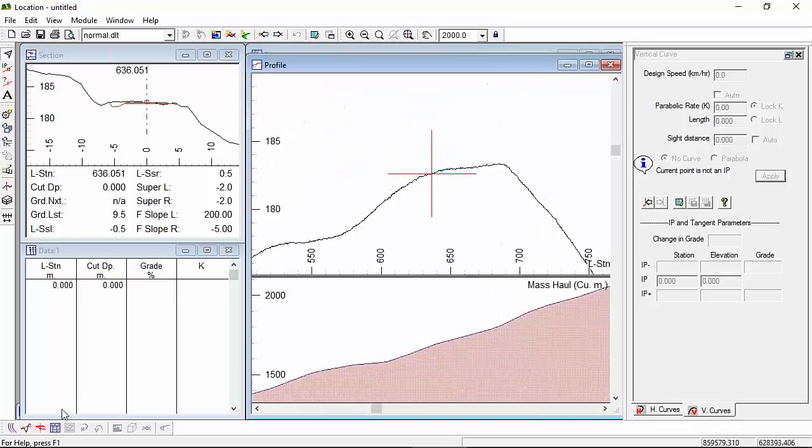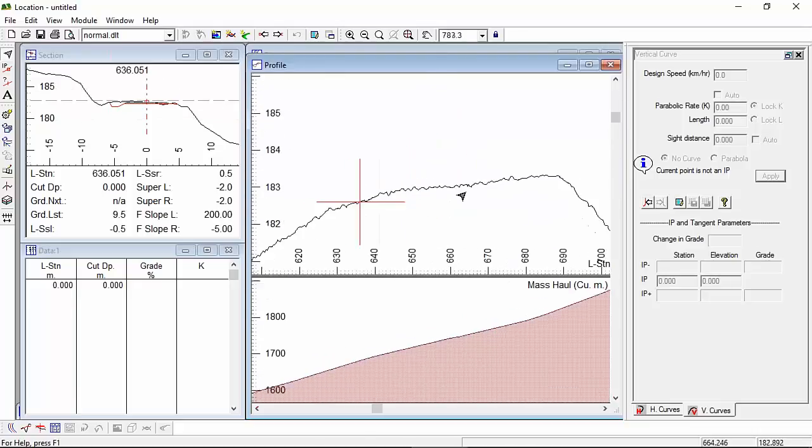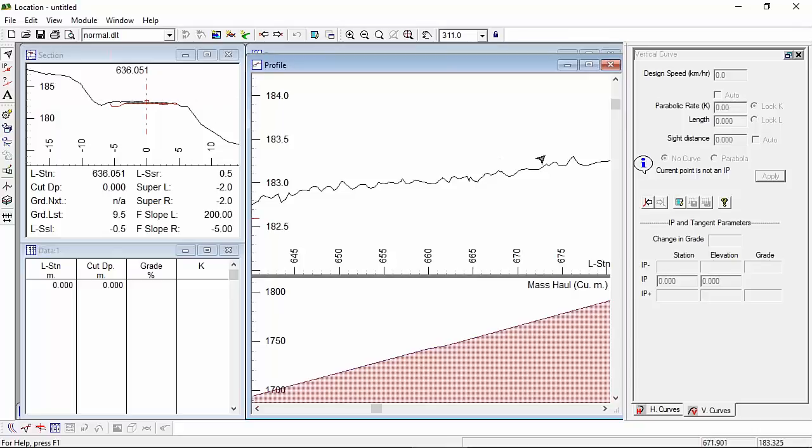I don't have a vertical yet. The vertical is just showing the ground. Kind of interesting to look at the shape of the ground that you get from this LiDAR survey. We're actually tracking along an existing alignment, so you would expect that to be smooth and continuous. But what you're actually seeing here is about a decimeter plus or minus error in the LiDAR data. I don't think that's going to affect our volumes too much, but it's just kind of interesting to see that.